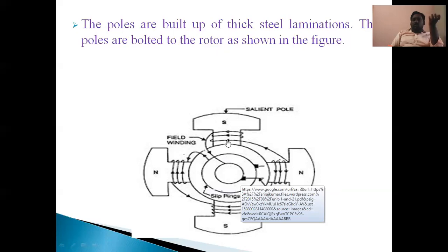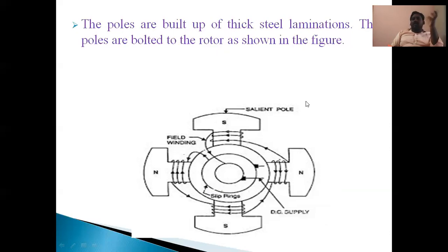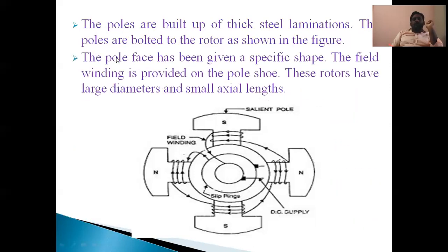When current flows to the coils, the required magnetic flux is set up. This total magnetic flux is rotated with the rotor, which is why it is a revolving magnetic flux. When this revolving flux cuts the stationary stator armature conductors, EMF is generated in the stator. Then voltage can be collected across the stator windings' three terminals, because it is three phase. So that is the nature of a salient pole type rotor.